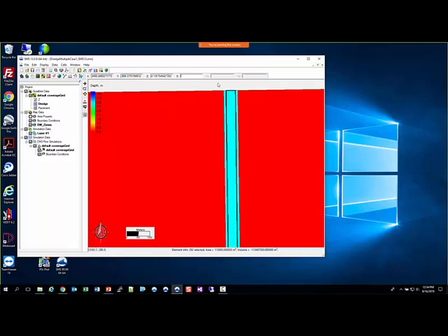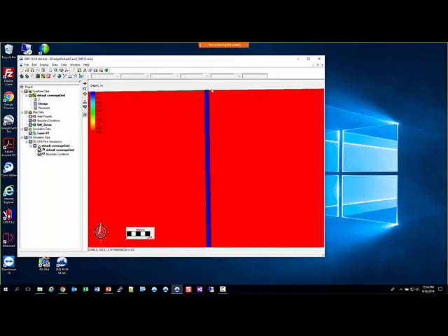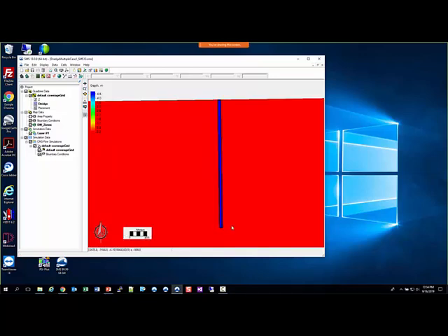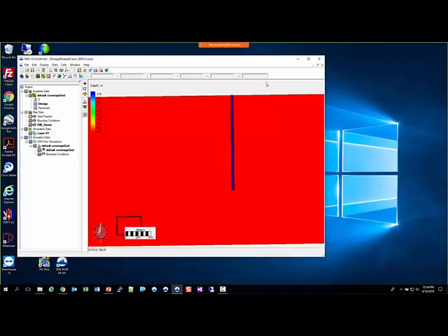Let's select everything, get rid of it, and put a 6 in there. Hit enter, and then we see we've got these values modified. And so that has selected the cells that we need in our dredge module for dredging and given the value of 6 meters deep to be our trigger depth.